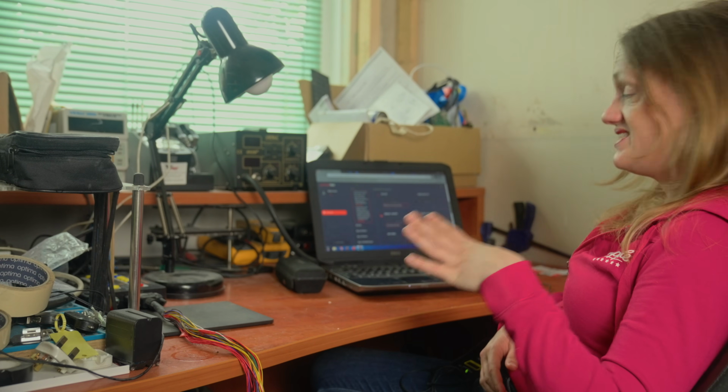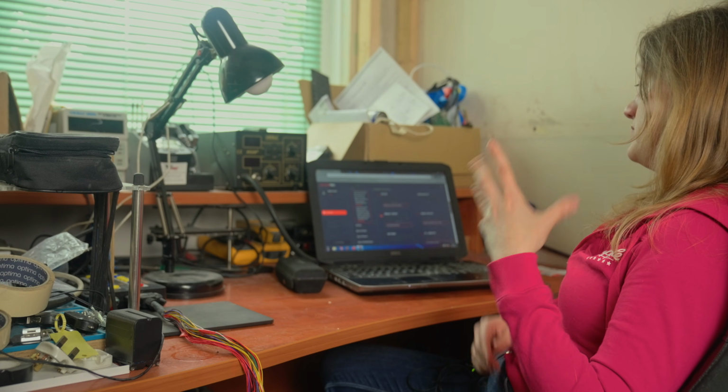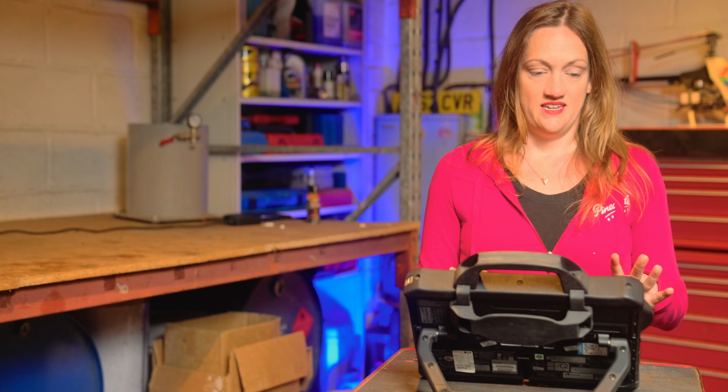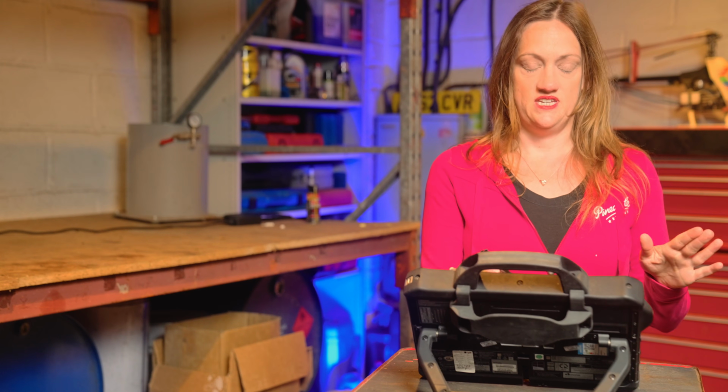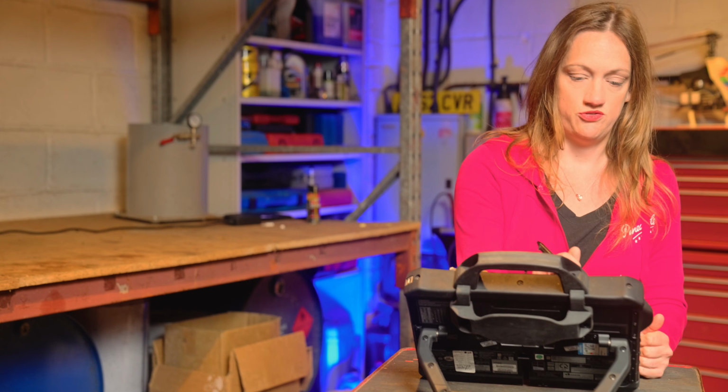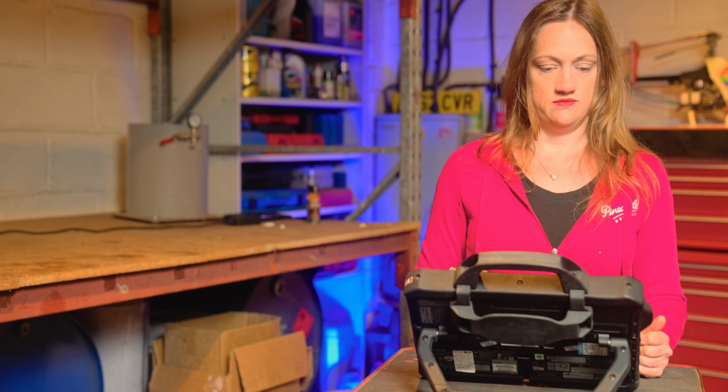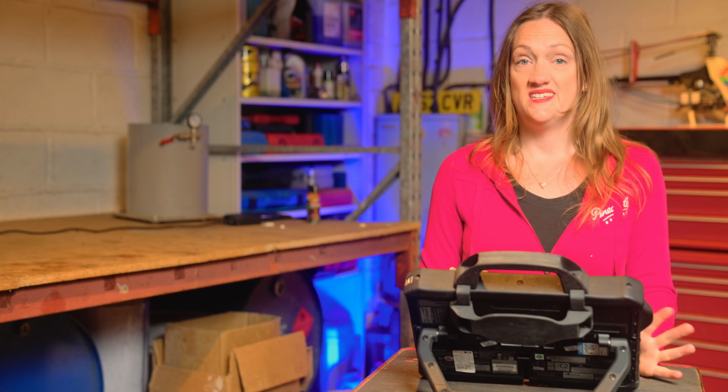Normally when mapping a car I have to make a lot of manual changes, but in this case this is such a common thing for this type of car and this engine that there's actually a plug-in for turning the swirl flaps off. So all I need to do is click on it and the map is created automatically. Now all I need to do is write my new file to the ECU, and that just requires me clicking on the file and uploading it. So in a couple of minutes that'll all be done.